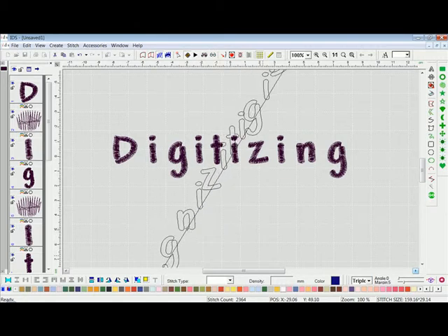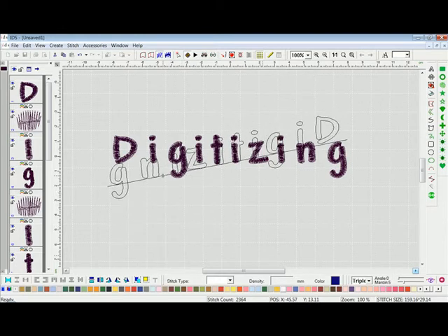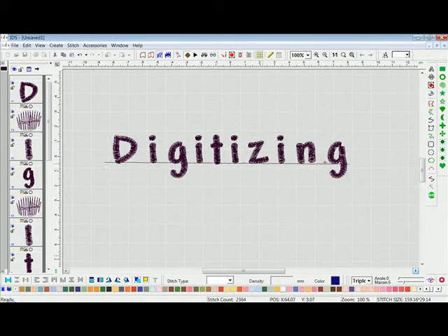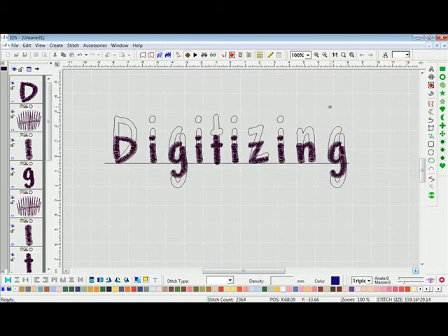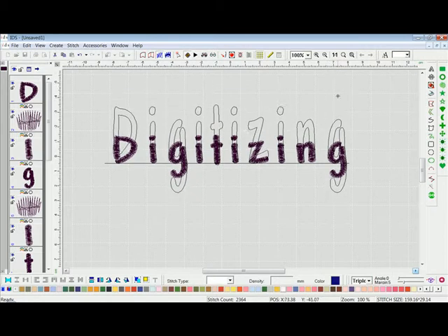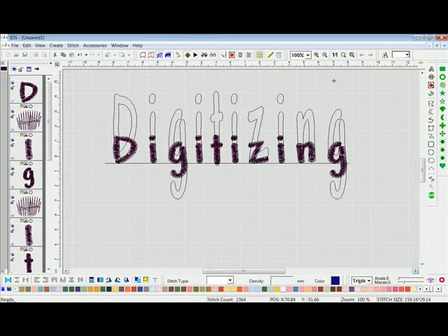I can drag that all the way around. It will go backwards, stair stepping, and I'll bring it right on back. I do have one last arrow on the right hand side. It's pointing up above the last letter. As I place my cursor over that arrow, it'll turn again into a crosshair, left click, hold, and drag, and it'll stretch my letters from the bottom of the baseline, or the bottom of the lettering, and up.